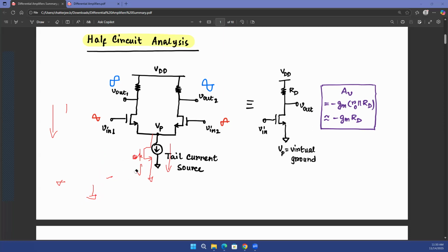That is why instead of applying a voltage source, people like to use a current source, as I had shown earlier. Let me just redraw it back again. You have a current source here, you have a transistor, you connect it in a fashion similar to the current mirrors, and then whatever current is flowing here will be the same current that is flowing here, irrespective of the resistances. Right? If the lines or the wires themselves have resistances, it doesn't matter.